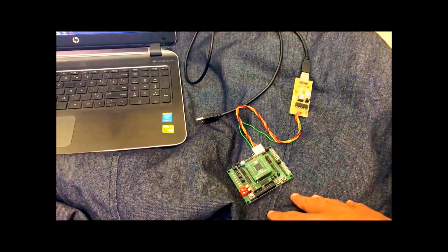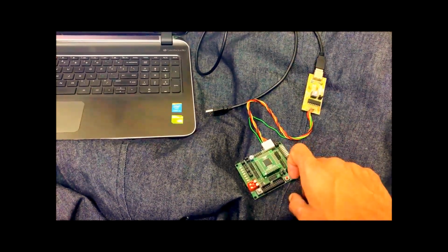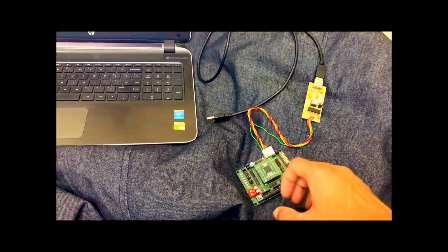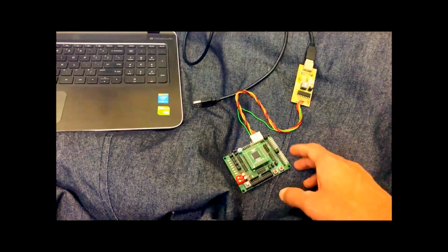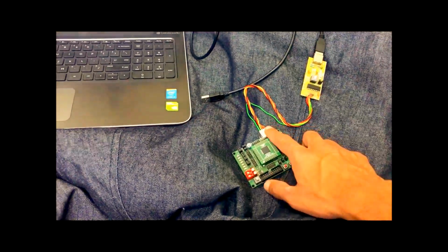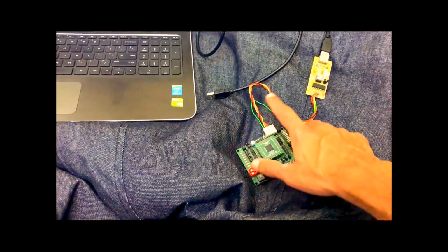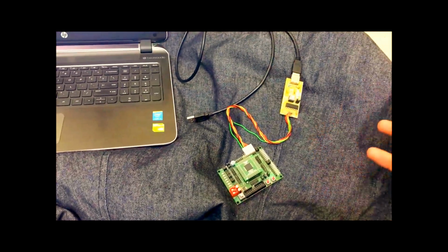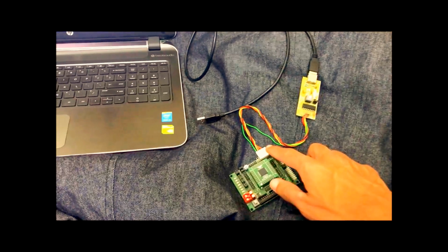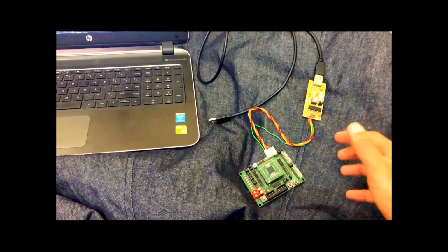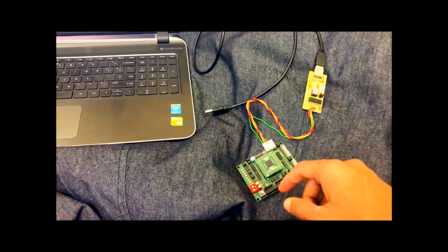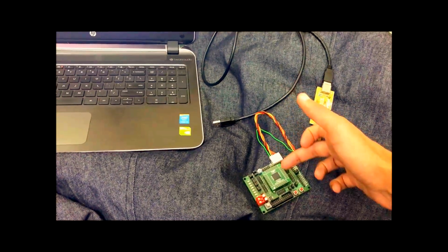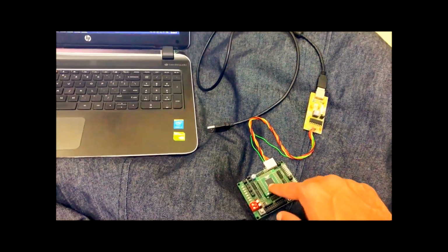And here's my development board, which has the microcontroller LPC2138 on the top, and then you have so many pinouts, probably for GPIO or SPI or so many peripherals. Then you have some UART port here, which is used for the programming. This is the programming circuitry. This is also nothing but a USB to serial converter, because in laptops we do not have the serial port provided. We have only USB port, so one circuitry is needed which converts the USB to serial, and here you will get the serial data, and the serial data will be downloaded to this microcontroller.